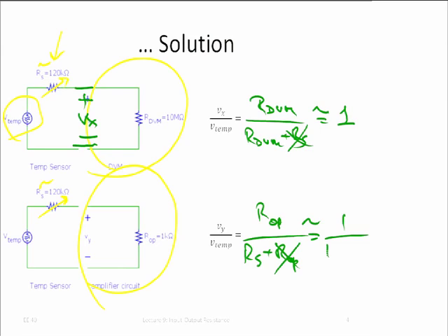Right? Makes sense? So what apparently happened when I connected the amplifier circuit is that first my signal was divided down by a factor of a little bit over 100. And then afterwards, the operational amplifier kicked in and put back that factor of 100. But overall, of course, 100 over 120 is still a little bit less than 1. So overall, I actually put in an attenuator. And that's exactly what I've seen here. The blue curve, right? That is 100 divided by 120. Okay? That's a little bit less than 1.